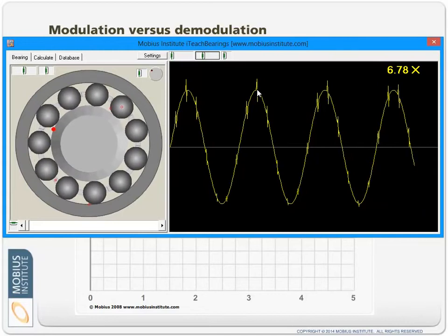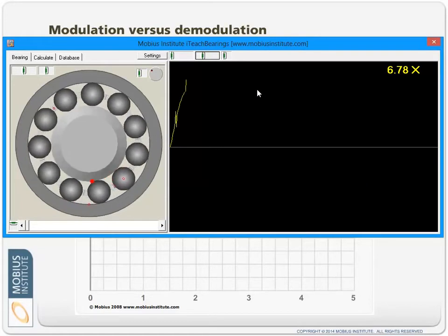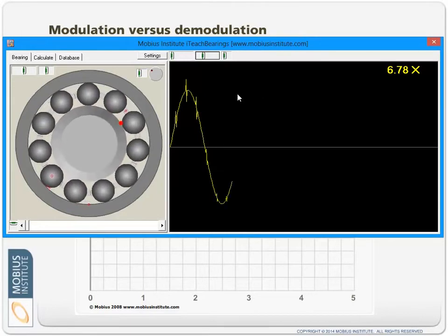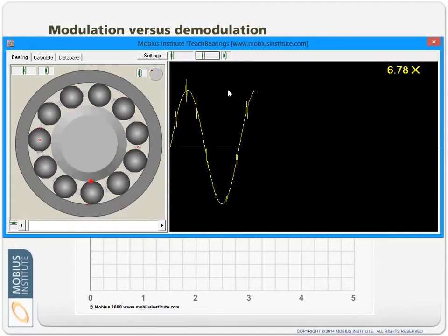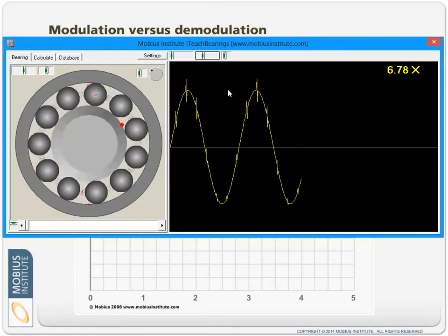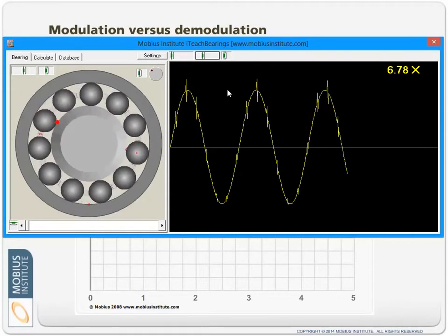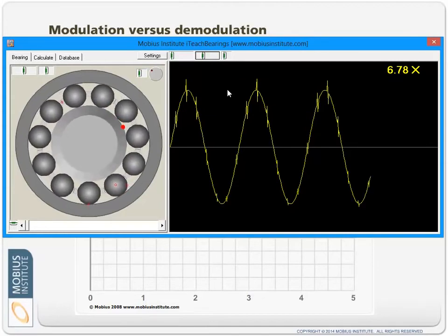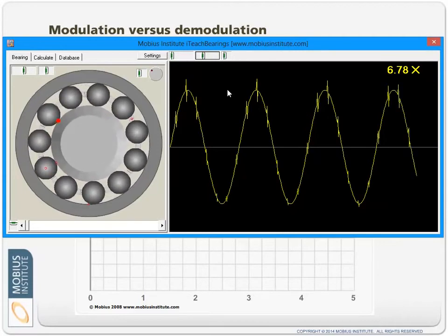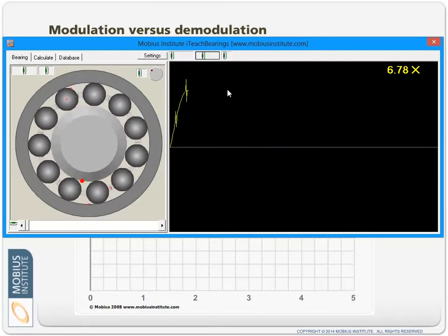There's just a little bit of impact vibration when that little red spot, or where the damaged area comes into contact with the rolling elements. So here and here. Now, in my illustration here, my little simulation, I'm exaggerating that amount of vibration. So the fact is that if we simply took the raw vibration from the accelerometer and looked at it as a time waveform, we may not see it. In fact, in the very early stages of a bearing fault, we won't see it. If we looked at it in a velocity spectrum, we won't see it. There are some other issues at play here related to duty factors and limitations of the FFT and so on. But we can use some smart technology.